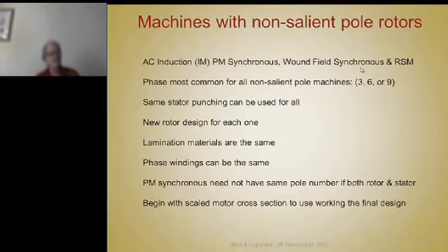For example, a 12-slot stator and a 10-pole rotor, permanent magnet machine, you cannot generate 10 poles with the stator with 12 slots and 12 coils. It's impossible. But I can wind that motor with 6 coils, 2 coils per pole, 180 degrees apart, 6 coils, every other tooth has no coil on it. And I've only really created 4 poles per phase, but that runs very nicely with a 10-pole permanent magnet rotor. So that's an interesting difference.